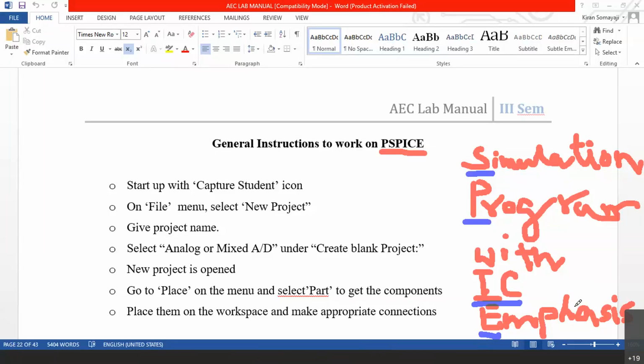Now, for a resistor, it is quite easy. It is simply going to follow Ohm's law. So based on the value which you give, the computer software will not have a lot of work. It will simply apply that Ohm's law slope, I equals V by R. So that way it is basically a mathematical slope. That way it will apply for a resistor. Even for a capacitor, it is not really very tough. X equals 1 over 2 pi f C. That is the formula which is going to be applied by the simulator. Here the simulator is PSpice itself.